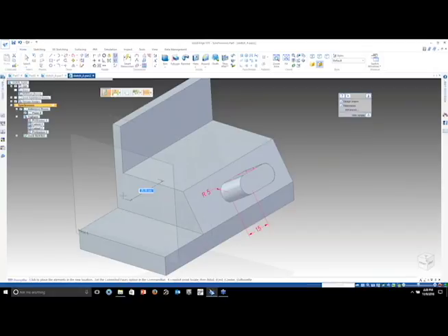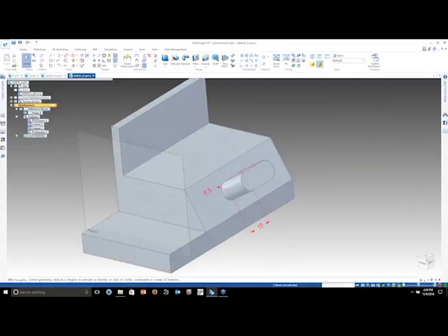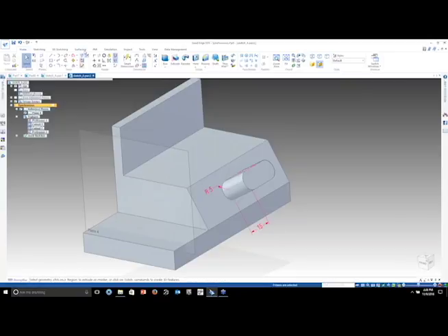How do we draw on a location that there is no face or reference plane? All right, we can easily add reference planes in Synchronous to sketch on. So just by using a coincident plane, attaching it by clicking that face, you notice we automatically get an arrow on the reference plane. So I'm going to grab the arrow pointed at me and just say, let's move that out 20 millimeters. All right, so now we have a reference plane where my sketch is going to be.